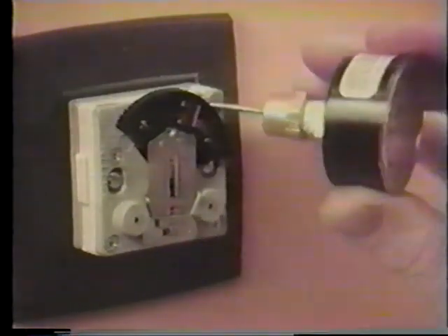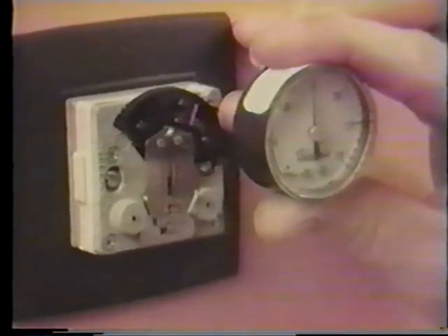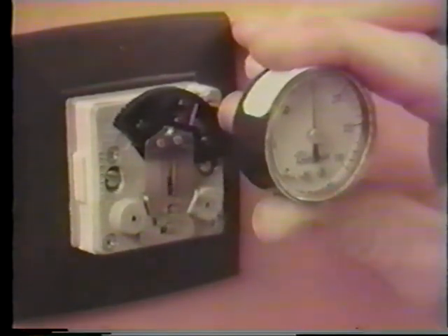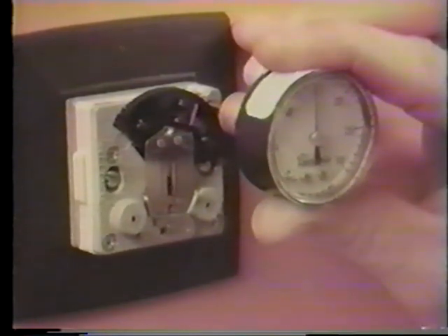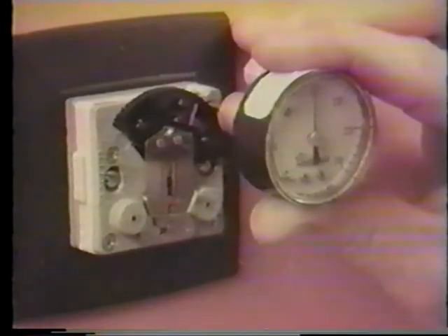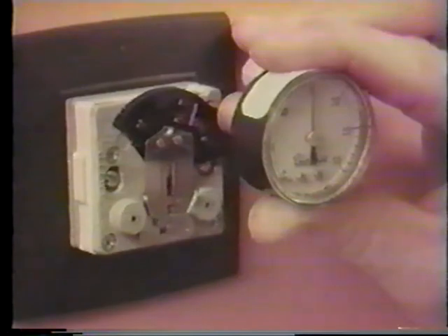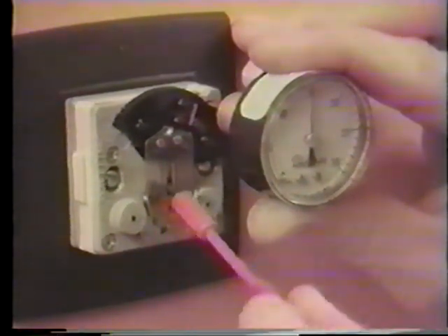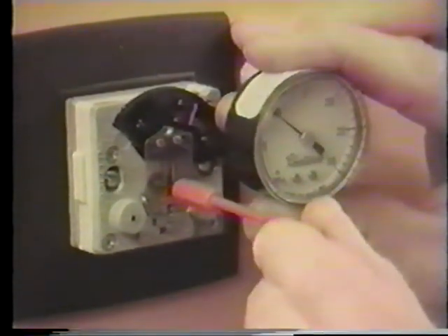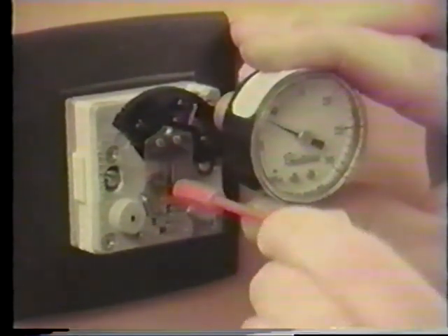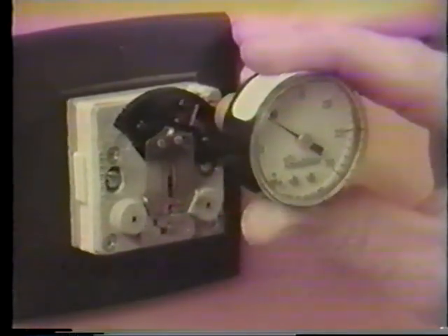Insert the gauge adapters so that the branch line output of the thermostat can be measured. Take care not to touch or breathe on the bimetal, or the sense temperature readings will be inaccurate. If the branch pressure is not 9 psig, use a 1/16 inch hex calibration wrench to turn the calibration screw until the branch line pressure indicates 9 psig. The thermostat is now calibrated.